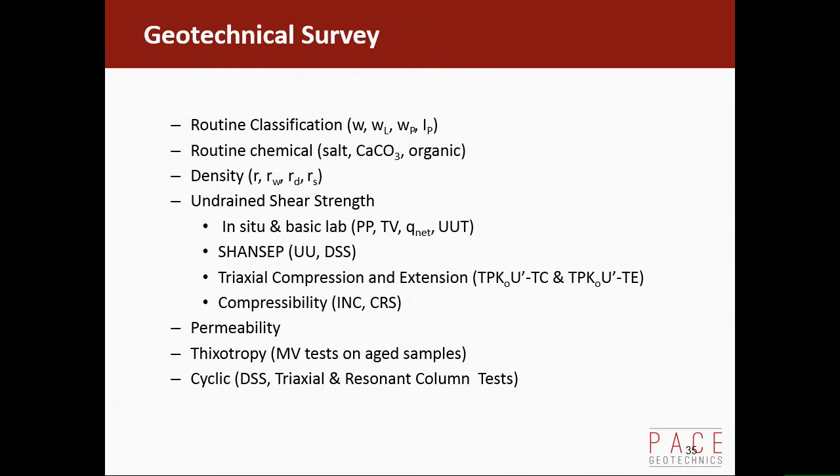And we did a full geotechnical survey, all the usual stuff there, and for that sort of development you do some quite advanced testing, like DSS, direct simple shear, where you put a little sample of soil like that. This always amazes me. It's literally 60 millimeters square by 19 millimeters high, I think, in a machine like that. And you put a thick rubber membrane on the outside and allow for that, and you've got this really soft clay, and you work out the strength from that, by shearing it horizontally. There's nothing simple about direct simple shear when you're actually doing the tests, but you get good quality results from it, to be fair.